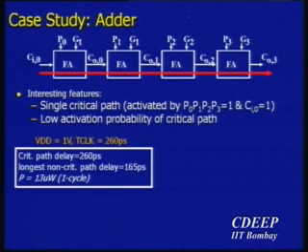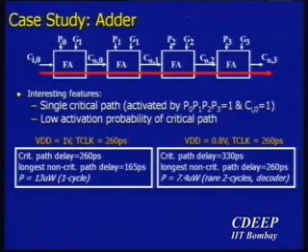You've got to play with the square root function a little bit to actually get the right kind of critical paths. It turns out that if you scale your supply voltage down to about 800 millivolts, still keeping the same clock cycle, 260 picoseconds, now what happens is some of these operations are going to be 2-cycle operations, right? And doing that, just because you've been able to scale it down to 800 millivolts, the power consumption reduces to about 7.4 microwatts. But occasional 2-cycle operations.